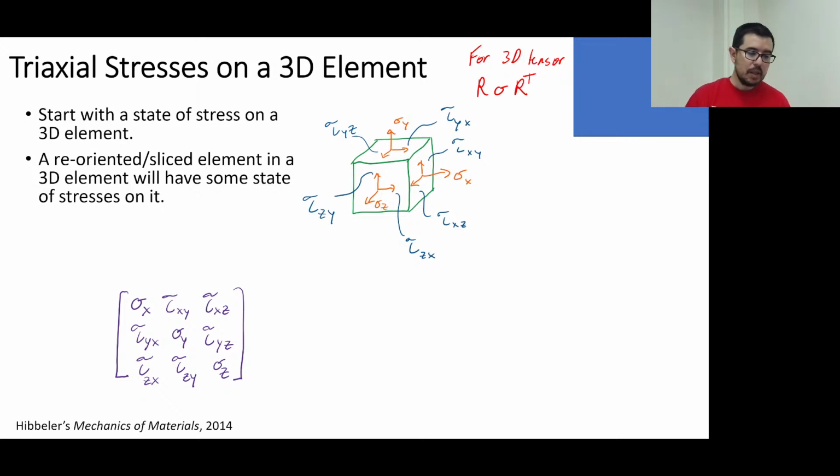And what's weird here, though, is sometimes you want to do a couple of rotations. So you do one rotation about one axis, and then you do another rotation about another axis. Okay, but that can be captured in a rotation matrix. The rotation matrix ends up being the matrix multiplication of those two rotation matrices that you've created, right? Because you remember we said, hey, this is the rotation matrix for rotation about x, this is rotation about y, this is rotation about z. Okay? Typically, we've been looking at xy planes, so our rotations have just been z rotations.